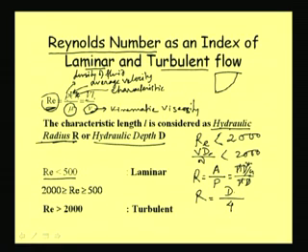And we know that in pipe flow it is less than 2000. So if I write V, and in place of d, I write 4R, over nu, then if I divide this 2000 by 4, it becomes 500. So d by 4 is nothing but we can replace this as R. So V R by nu is the Reynolds number expression for the channel.